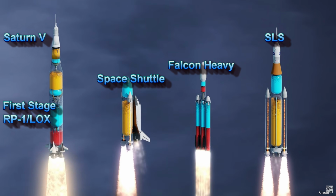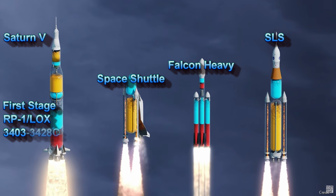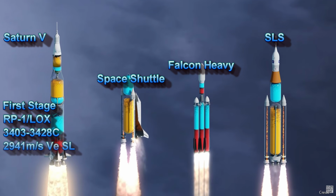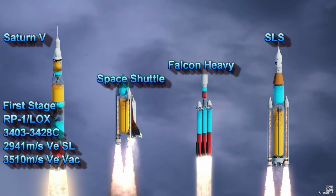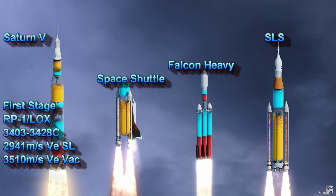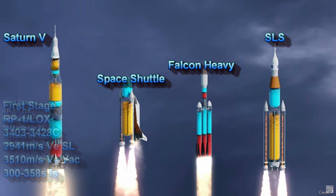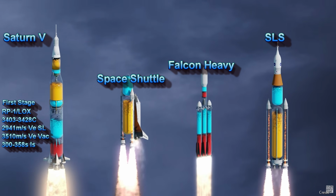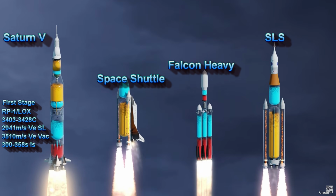RP1 in oxygen produces a combustion temperature of about 3,403 at sea level, adjusted to about 3,428 in vacuum, and an exhaust velocity of 2,941 meters per second at sea level to 3,510 in vacuum. That gives us a specific impulse of 300 to 358 at best. This difference is created by the back pressure in atmosphere, which slows exhaust velocity, and how the nozzle is optimized, short for sea level or extended for vacuum.